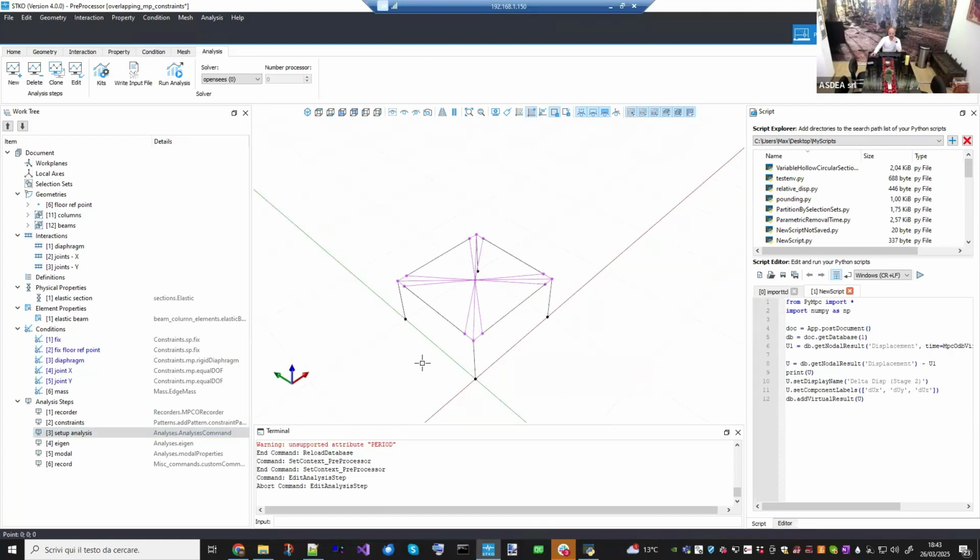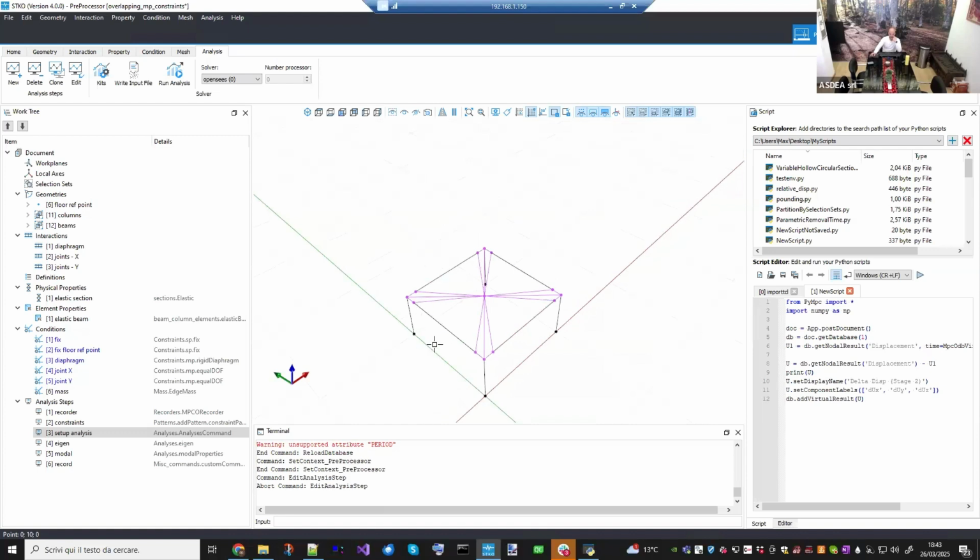Now, a second thing that we implemented in OpenSees is that the constraints can now be treated incrementally, because before in OpenSees there was not a consensus between the different kinds of constraints. If you applied a constraint in a second stage of the analysis, some constraint handlers were applying the constraints incrementally and some others were applying the constraint globally.